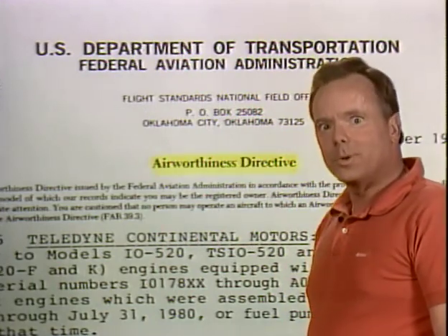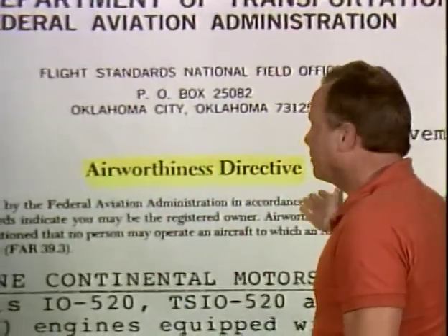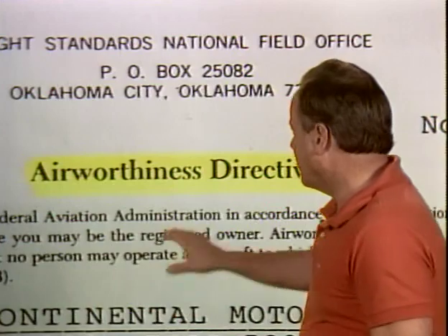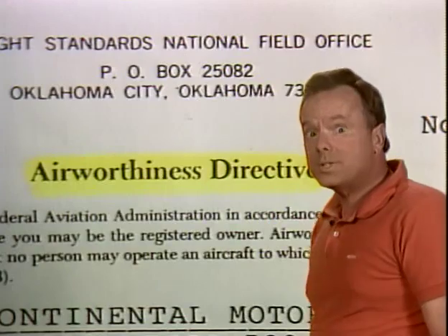Now, airworthiness directives are letters the FAA writes to owners or operators of aircraft saying some defect has to be repaired within a certain period of time. The thing you need to know about these is that these are federal aviation regulations and they must be complied with unless a specific exemption is granted. So you must comply with airworthiness directives, and airworthiness directives of an emergency nature require immediate compliance upon receipt. So if you have an emergency AD, you must comply with it right away.